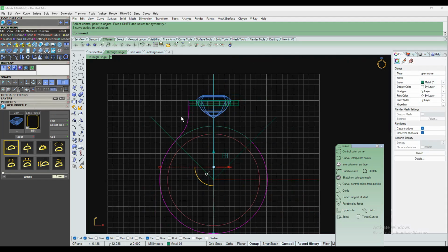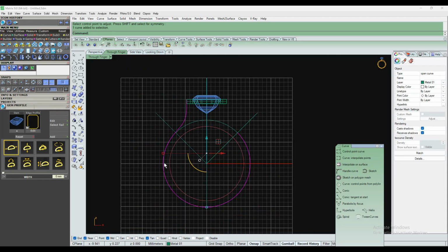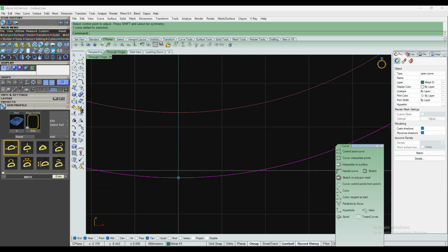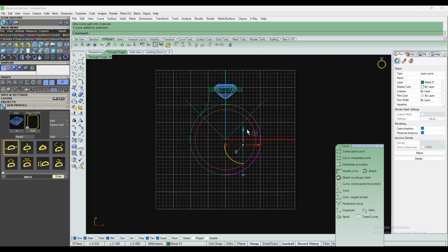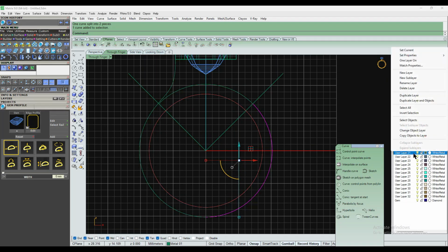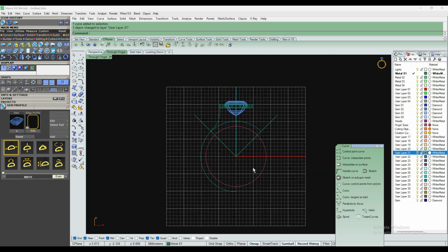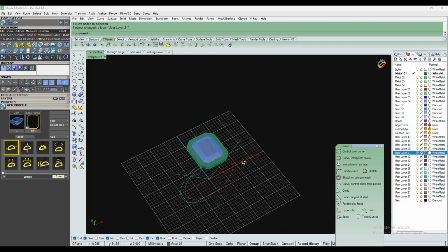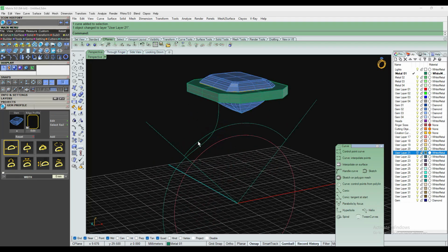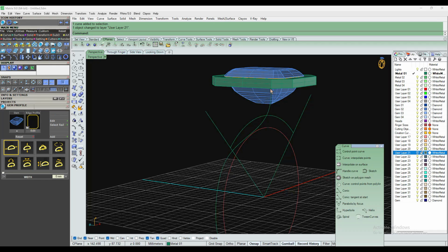and then select. I want similar from this point to this point, or I can split from here, we can mirror it later. So for now, let's split with the point and click here. Make sure the quadrant option is turned on and click here, so it will split and move this object to another layer. Okay, so this distance is very important, and our width is very important.